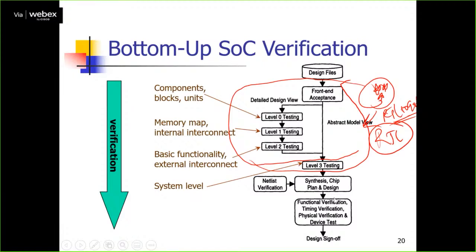So do the pre and post routing verification, pre and post CTS verification. With respect to that, you do the timing, physical and device test, and then sign off.